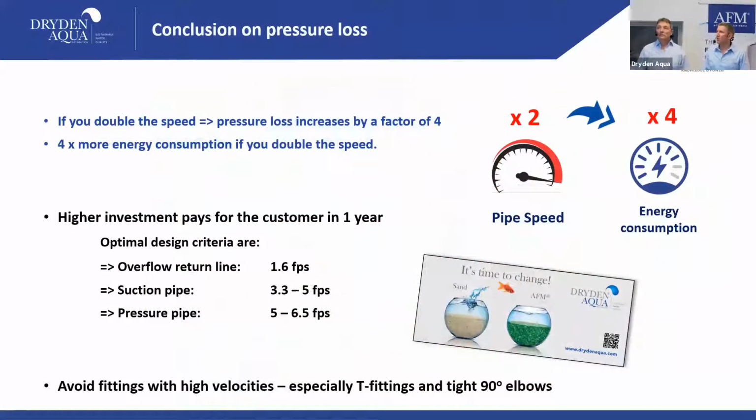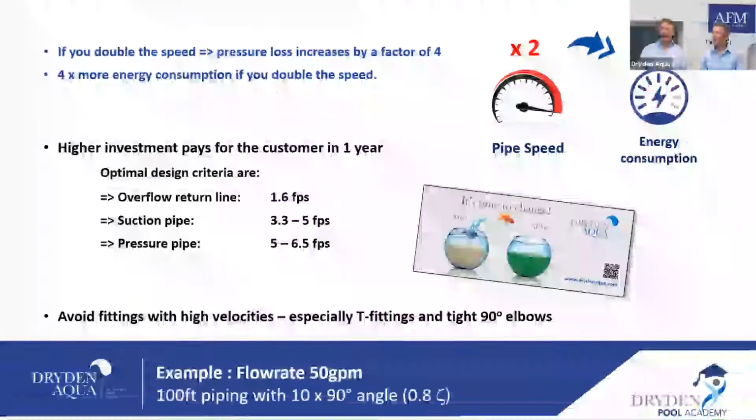Conclusions on pressure loss. The main takeaway from this piece is really, if you double your speed, then your pressure loss will quadruple, or vice versa. If you halve your speed, then your pressure loss will go down by a factor of 4. If you lower it by a factor of 4, that means you lower your energy consumption by a factor of 4 as well, right? Absolutely. If there would be no resistance, no friction, no pressure drop, you would not need any energy. Yes. So pipe speed is the key here. Okay.